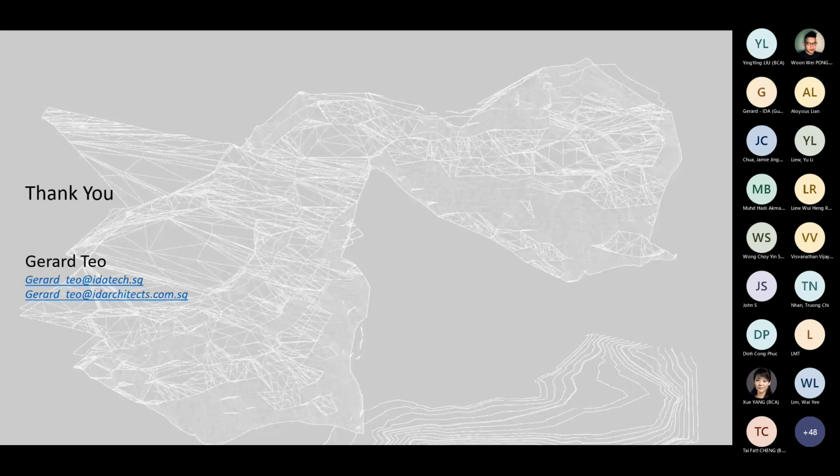Okay. So actually, we do extract a lot of different information from Excel because a lot of info comes to us in Excel as well. But in this case, today's example, what I was showing was our BDIP template. So when we submit, we wanted to have these different colors showing all the different LSA elements. So we took that template, extracted the names, extracted the colors, and then pushed them into the existing Revit filters so that we could then prepare our submissions like that.